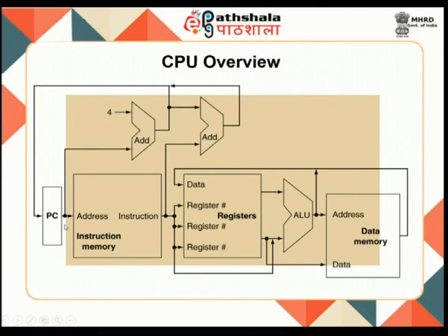Now, if you look at the earlier diagram, this is your primitive flow diagram, where we have just indicated it by means of points here. So, it is either the PC plus 4 value that will have to be loaded into your program counter, or it is PC plus 4 plus the branch displacement which will have to be added. That is one point.